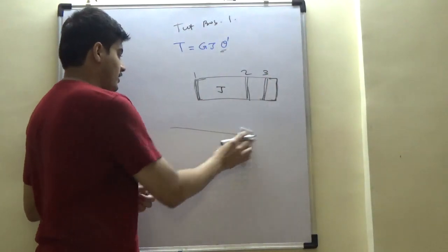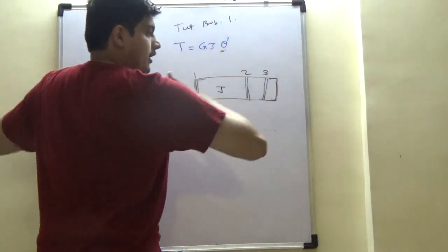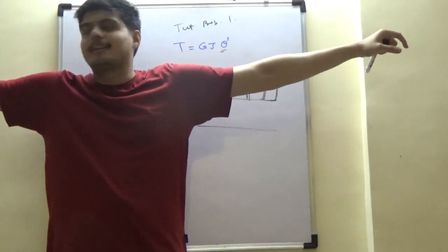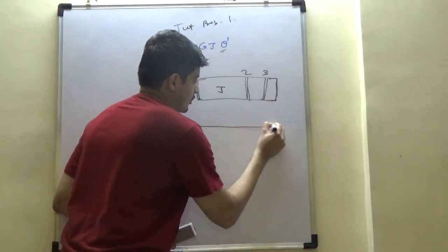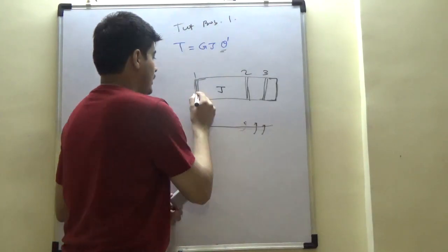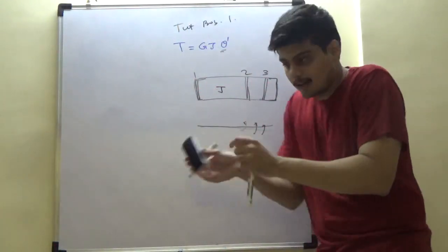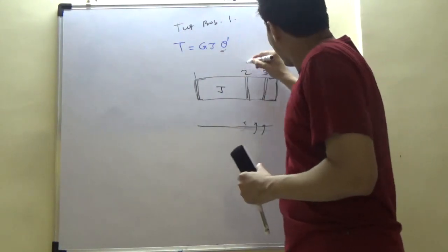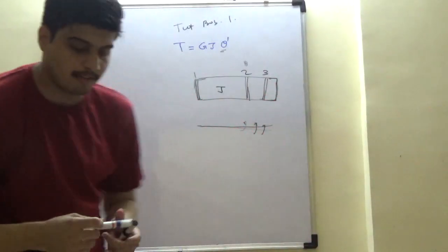So if this was my initial sectional view, the view from this side, if this is the aircraft which is parked, I am looking at it this way. This is the aircraft parked, you are looking at it this way, almost like a line, right? It is going to have this twist, and this twist is going to cause each of these 3 sections, section 1, section 2 and section 3, to actually increase in their angles. These are going to form different angles of attack. My goodness, aerodynamicists suddenly have a worry.